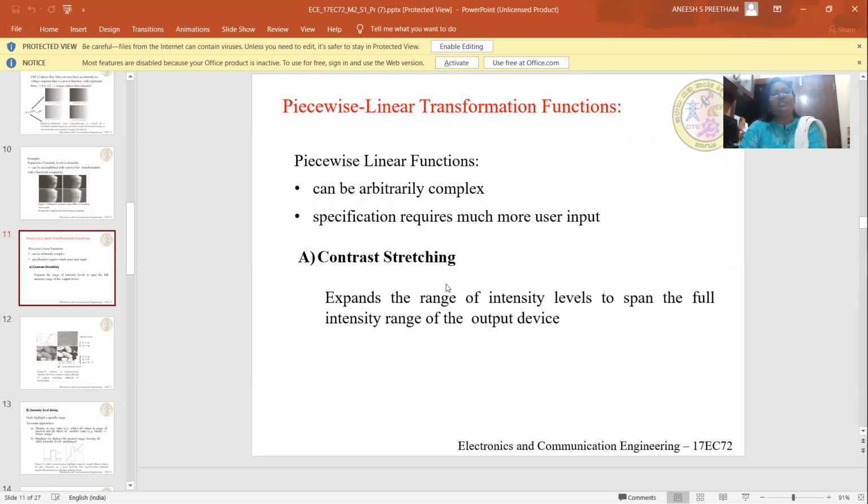The second reason why an image may be dark is that the dynamic range of the sensor on which you are imaging is very small. What I mean by dynamic range is the capacity of the sensor to record the minimum intensity value and the maximum intensity value. The difference between the minimum and maximum intensity values is the dynamic range of the sensor.